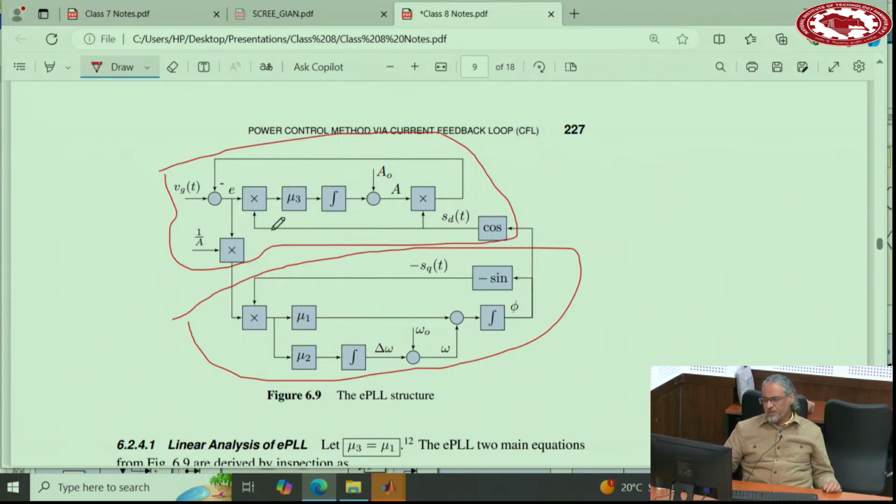The calculations are basically three integrators, one for magnitude, one for frequency, and one for angle. So basically three dynamics that search for the magnitude, angle, and frequency of this waveform and try to find them. One of them eventually finds the magnitude, one of them finds the phase, and one of them finds the frequency. And this is the rated value of frequency here. If you apply it, it will have a faster startup.